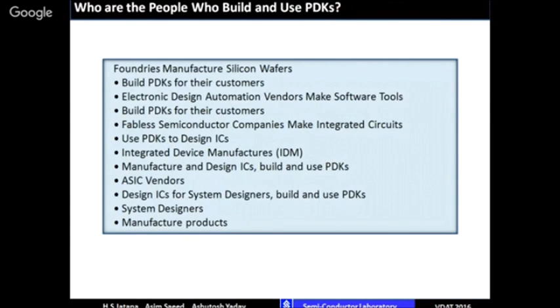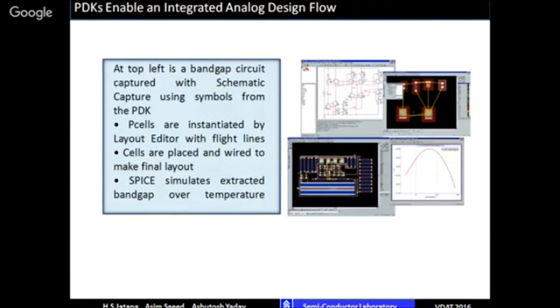And now, since the transistor sizes are falling, the mismatch becomes more, on-chip variation also increases, and with this the yield suffers. And nowadays people talk about design for manufacturability, design for yield. So what are those issues? Some of those issues are also highlighted in these PDKs, how to enhance the yield. So I will give you one example.